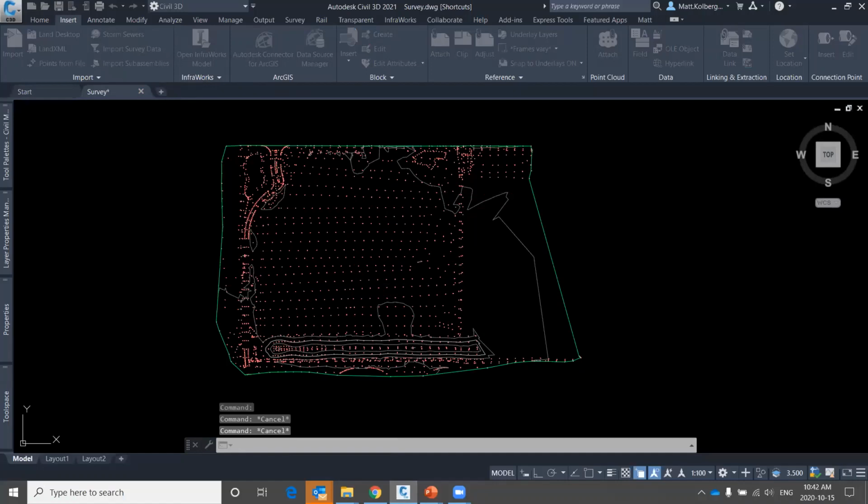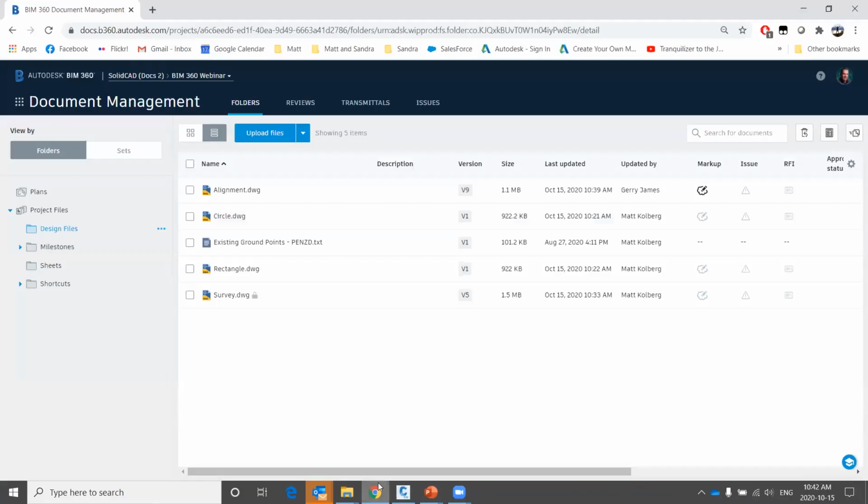Right, so you've invited the land developer to this BIM 360 project. So they log in and they see this, and they would love to have a look at this DWG file, but maybe they don't have Civil 3D or even AutoCAD installed. So they're going to call you and say, hey, I want to be able to look at that file. Can you make a PDF for me, or can you do something else for me before I can look at it? And then you'll tell them, well, we don't need that, because all you got to do is click the drawing. That's still refreshing itself.